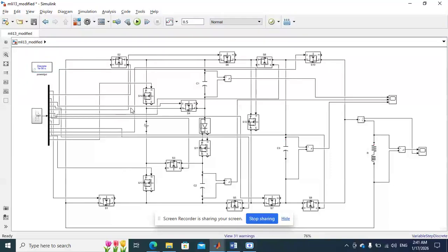This is the working of the inverter. This inverter consists of a single voltage source and 3 capacitors along with 14 switches. Here, due to the 3 capacitors the levels will be generated, and the voltage will be 6 times higher than that of the input voltage. Here across C1 and C2 the voltage will be equal to the DC input, and across C3 the voltage will be 3 times the DC input.